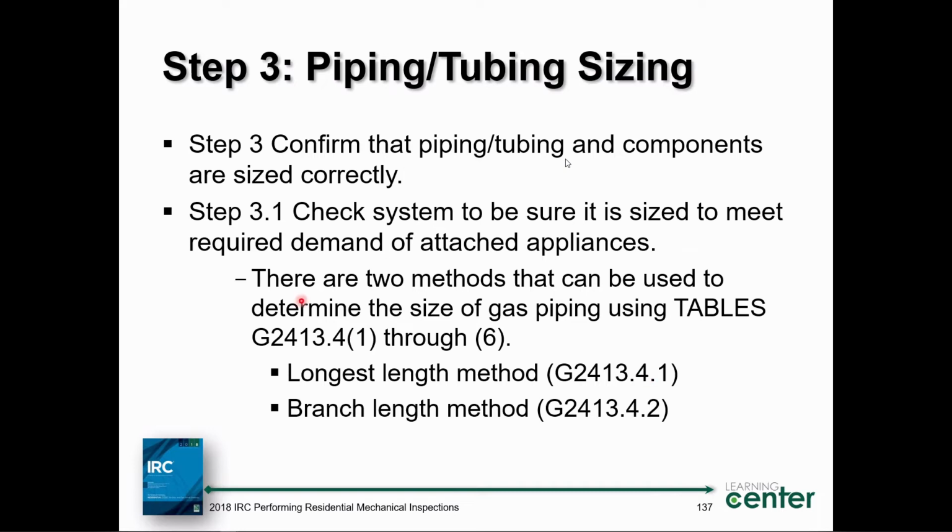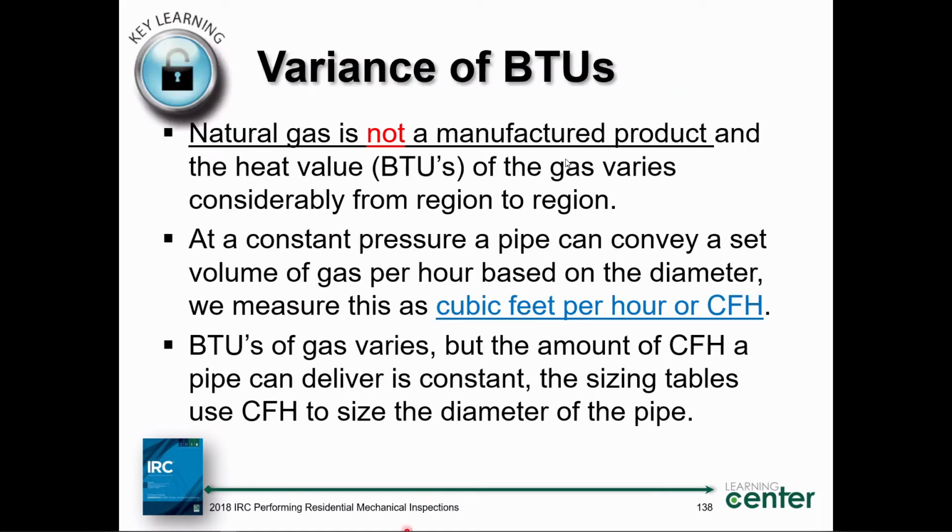So we have to ask ourselves a few questions before we begin any type of application. Like a plans examiner, we have to ask ourselves the question, what the heck am I looking at? Is it compliant with the code? If you look at it on the flip side, like you're sizing a gas piping system, you need to know certain things, like what's the pressure of the system? What's the pressure drop of the system? What's the specific gravity of the gas? What type of material am I using? Things of that nature.